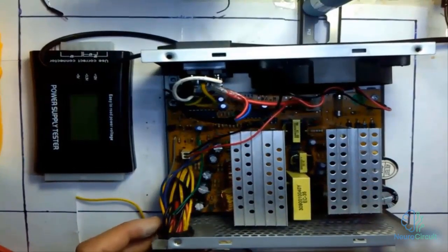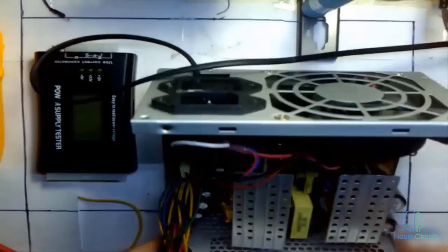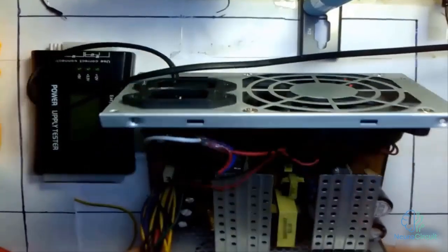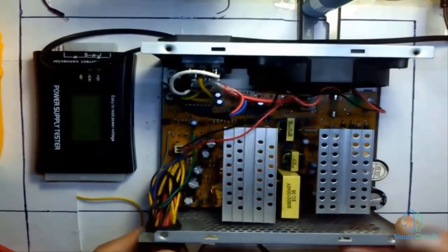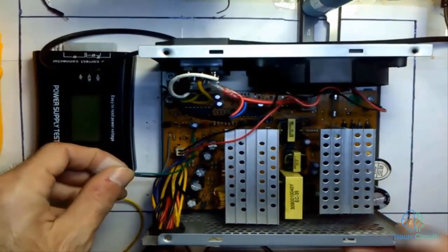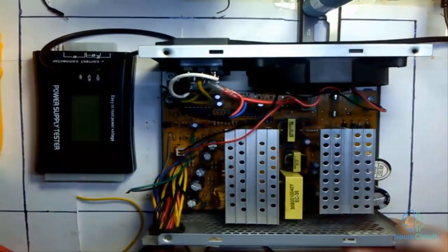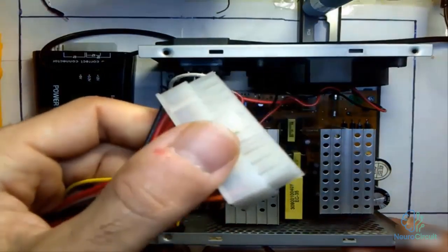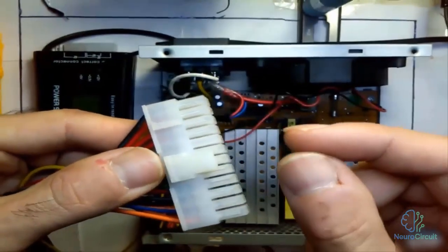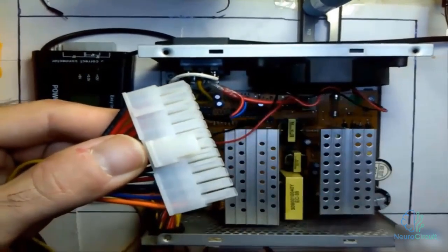Alright, here we've prepared a power supply and we're going to test it. You see, when you turn on the power supply, by plugging it in and switching it on, the fan starts spinning. This means the power supply is on. Of course, to be able to turn on the power supply, you can connect the green wire and the black wire that are located in this connector. You can connect them using a piece of wire or a pair of tweezers.